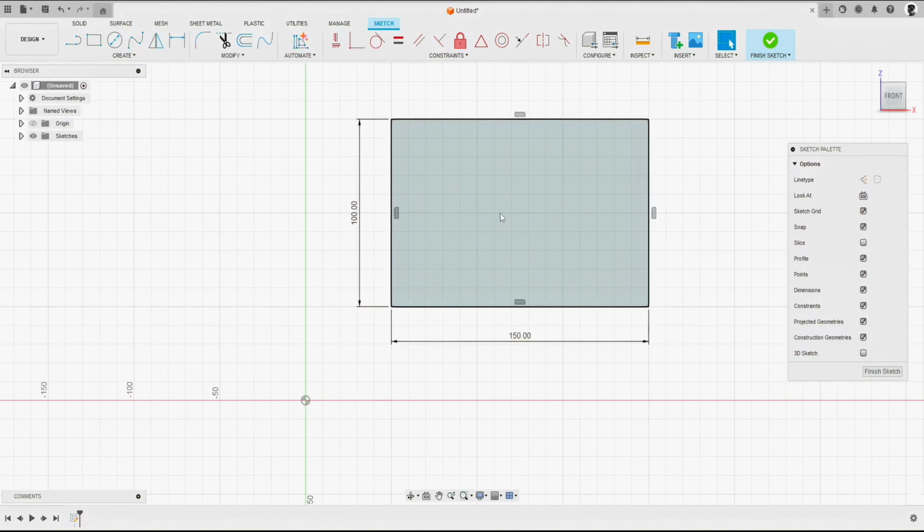And let's say that we wanted to add multiple fillets of the same dimension. We can do that by, again, choosing the fillet tool. We'll select this corner here. We won't input a parameter just yet. Let's say we want that to be 10 mil, and this one here. Okay, so now we've got both of those selected. Now we can enter the parameter. So in this case, let's go for 10 mil. Let's enter. And you'll see both of these are 10 mil.